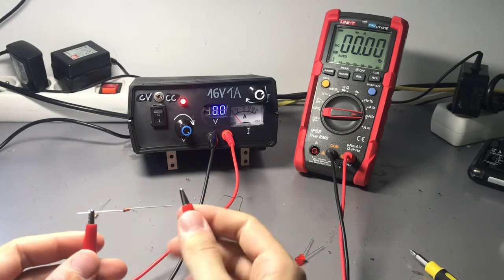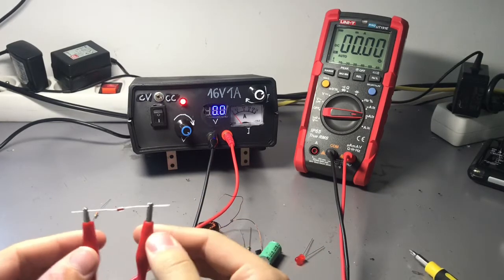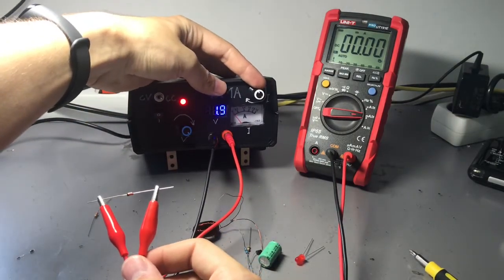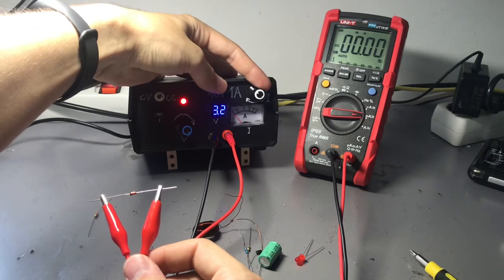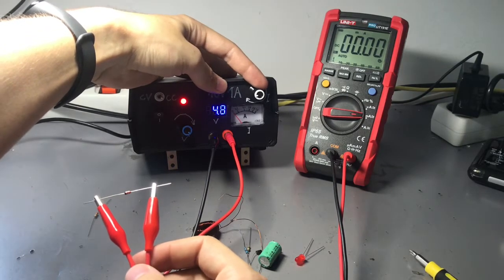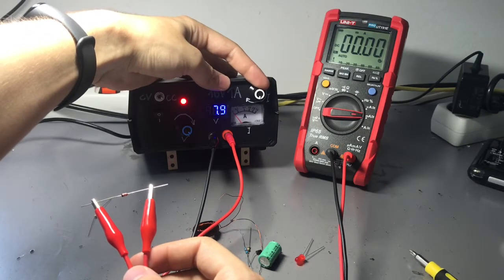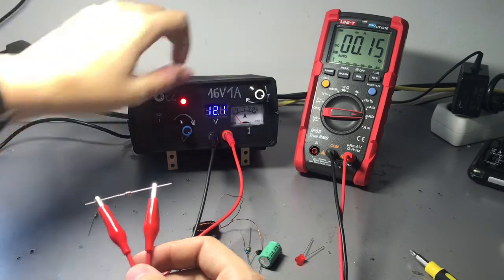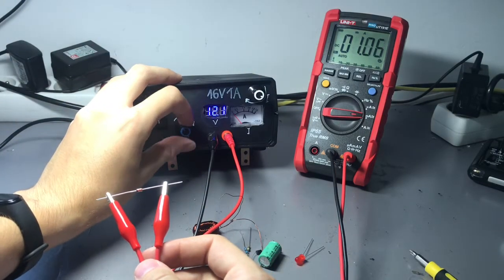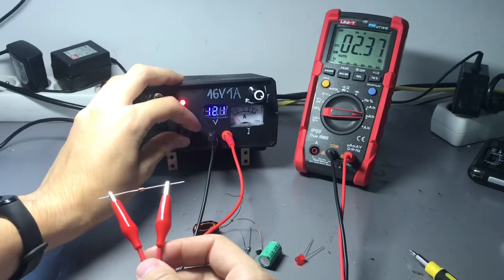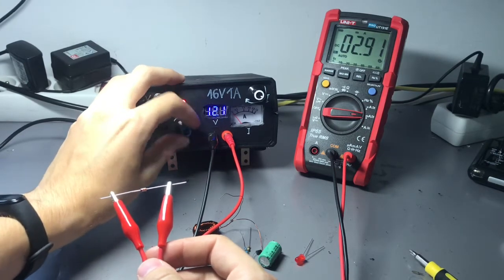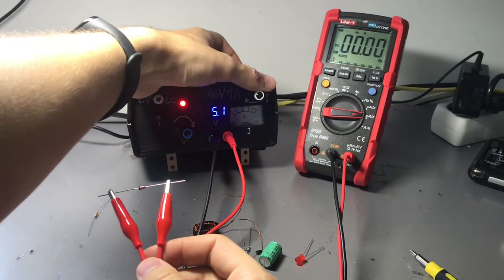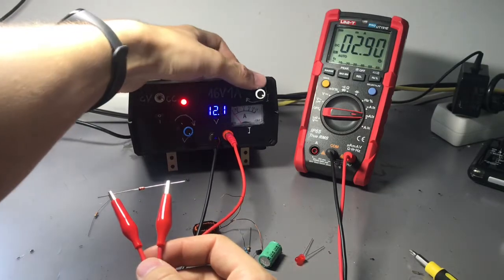So right now here goes this and this, and right now it doesn't conduct, doesn't conduct. With a normal diode it wouldn't conduct, but with this diode from some voltage it starts to conduct, as you can see. 1 milliamp, 2 milliamps. I increased the input voltage a bit. So as you can see, it's a Zener because my power supply limits it to 12 volts.